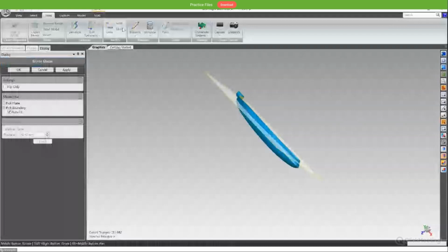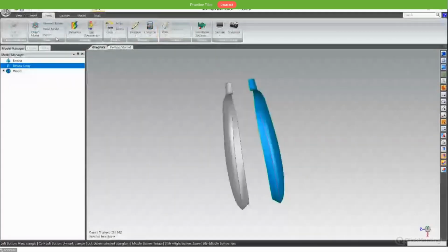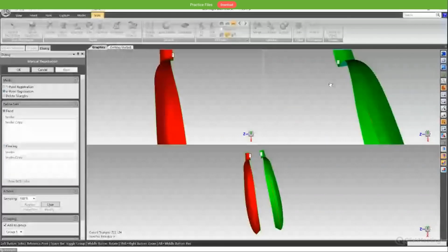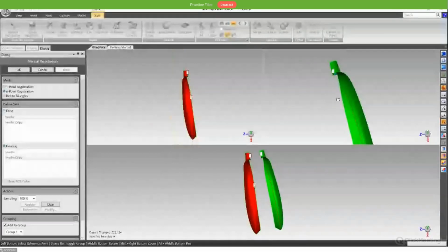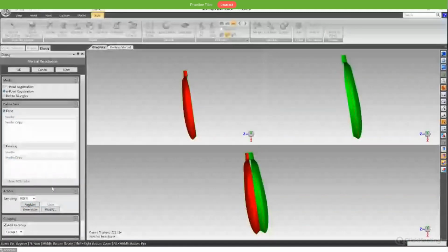And yeah, here you go. Then you just choose the scan section, select manual registration, use the endpoint registration, pick 3 points and do the manual alignment. Okay, something like this. And go with the registrator. And okay, yeah. So these two models have been aligned.